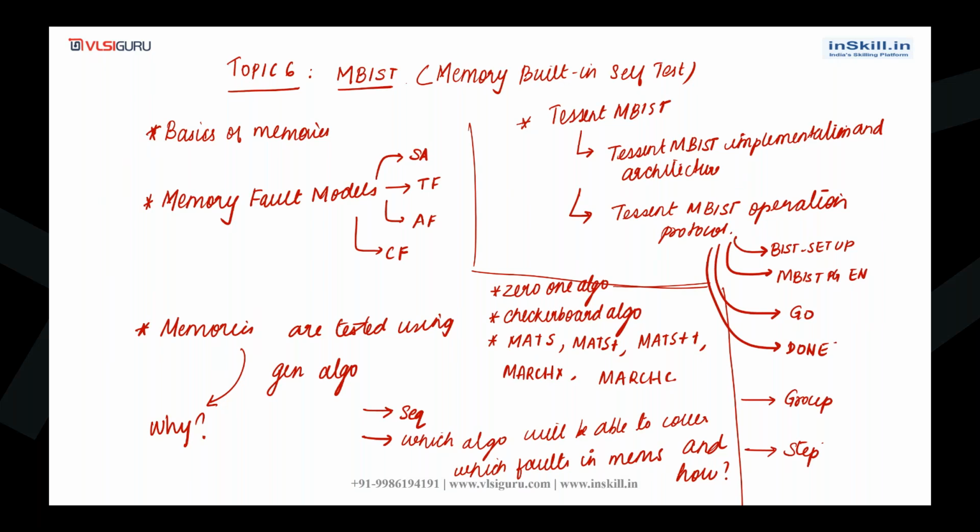These are all the things we will cover within Tessent MBIST: the implementation and architecture, and the operation protocol, with the BIST setup, MBIST PG enable, go and done signals, group and step.